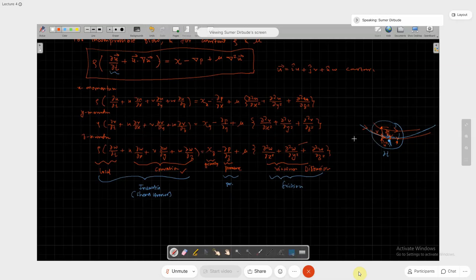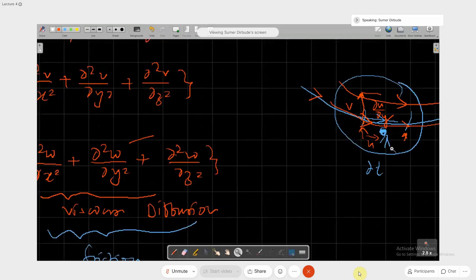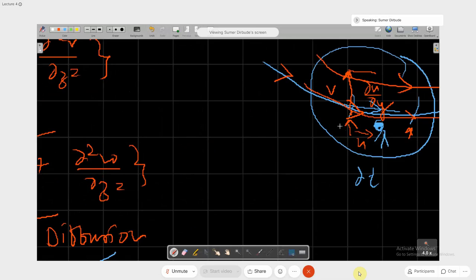But here, without any bulk motion also, you may have momentum transfer. So how can that be? You know that microscopically we have molecules, and these molecules transfer the momentum to nearby molecules. Okay. And this process is called a diffusion process. Momentum is getting diffused into another molecule, then that will transfer momentum to another nearby molecule. Similarly, the momentum is transferred from location A to maybe location B without any bulk motion, only through this chain of molecules. Okay. So this molecule passes on to that one, and similarly it will pass on to other molecules and finally to some location.